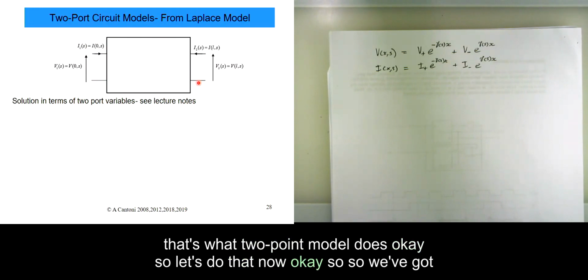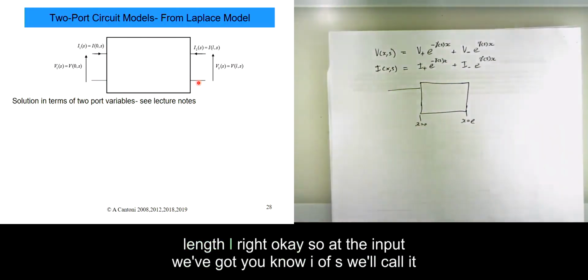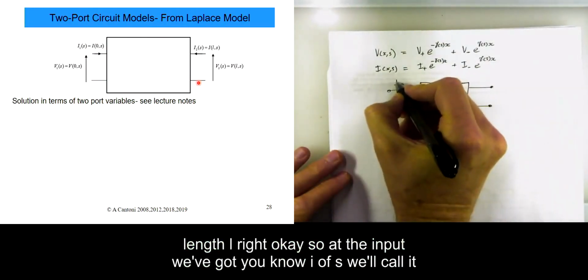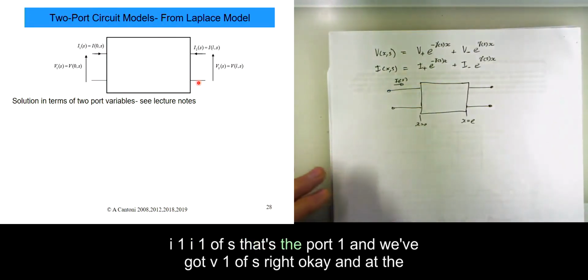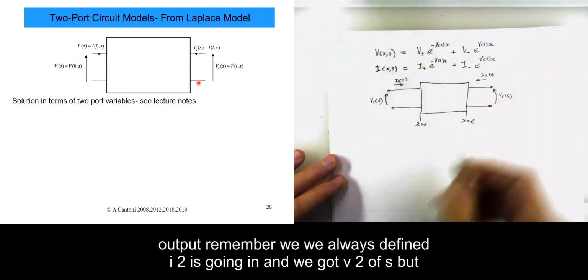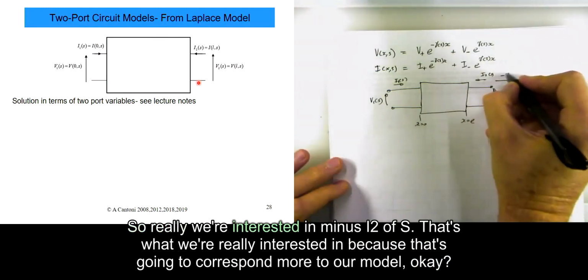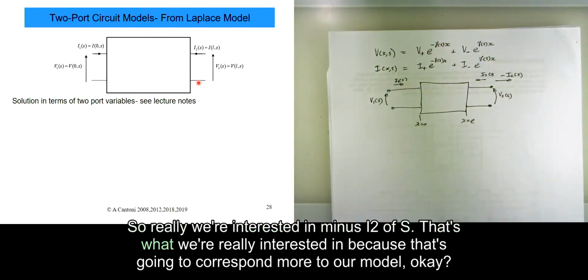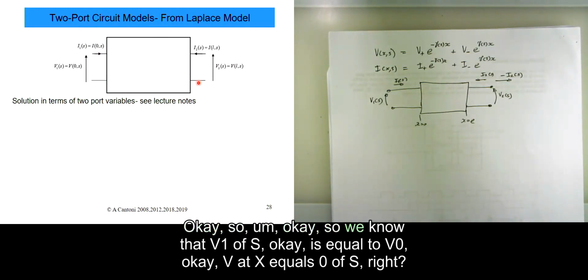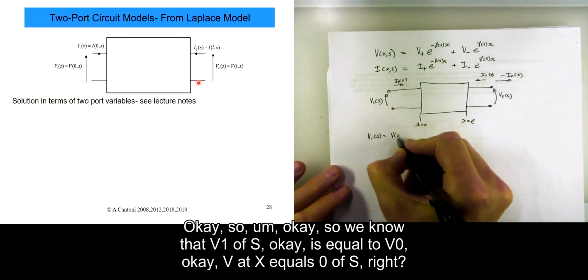So let's do that now. We've got our bit of transmission line. Here it's x equals 0, and here x equals some length L. At the input we've got I1 of s, that's port 1, and we've got V1 of s. At the output, remember we always defined I2 as going in, and we've got V2 of s. But in our model for the transmission line, we always had current going to the right, so really we're interested in minus I2 of s, because that corresponds more to our model. So we know that V1 of s is equal to V naught, V at x equals 0, of s.